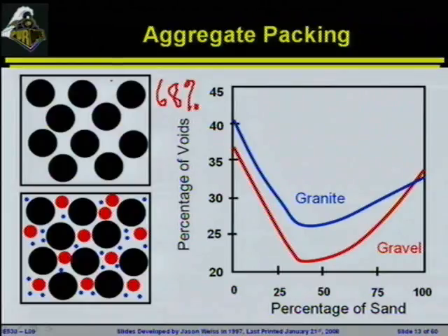That would mean that the paste in the system would need to be 32%. Quick with the math. So the rest of it would need to be 32%. And we talked about mixtures where we got to much lower than that, when we were on that first slide. So what we typically want to do is use a collection of different size particles to try to make the system more dense.